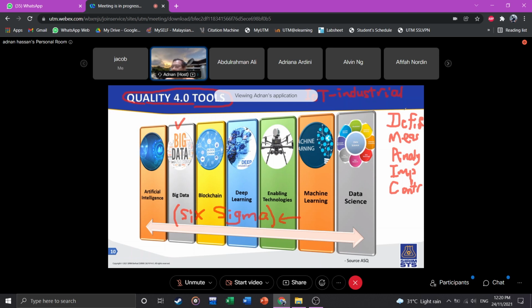What are measuring instruments? It can be simple devices. In the past, people used, for example, micrometer, vernier caliper. These are basic. And also can even use some sensors, for example, proximity sensor, can use digital devices to detect the distance, to detect the gap, to measure a deviation. Those are the sensing part where you collect data, and this data will be transferred into a data logger and then goes to computer to analyze.